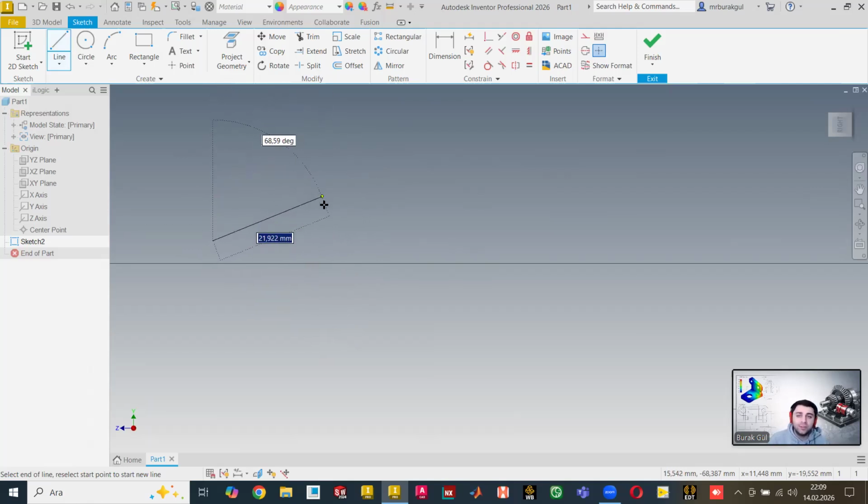We will choose it. And if I write here 20, for example, from my keyboard, I just clicked on 20, the size doesn't change anymore. And if I click on the tab button, now the size is not changing, but the degree, the angle value, is highlighted. The more I move my cursor, it follows it and the value changes.